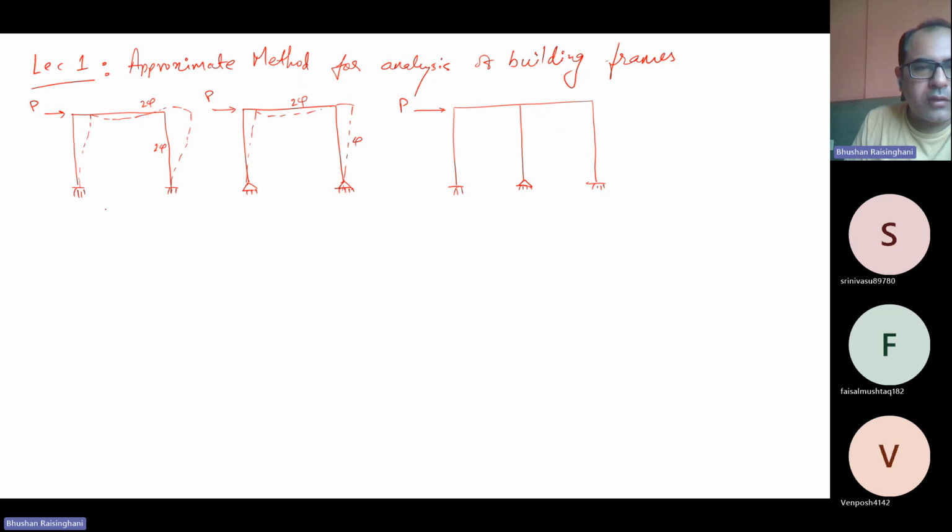And we had solved for the base reactions. What are the reactions at the base? And the vertical reaction, as it is a clockwise moment, this will be the anti-clockwise moment we have to generate. So this frame is behaving with a global clockwise moment, and the reaction will be an anti-clockwise moment. That is given by the two couples that we have. The same will be here also. Only thing is you will have a bending moment reaction here.